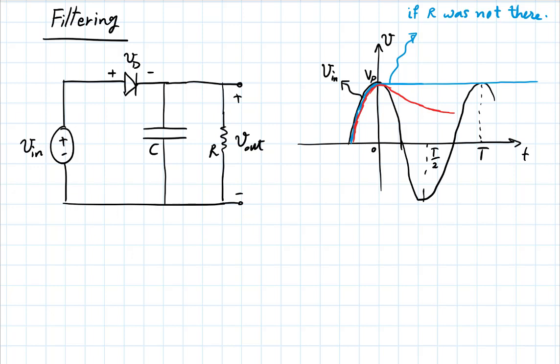Whereas in the other part of the cycle, the diode has become off. The input has been disconnected. Now you have an RC circuit, and you have an RC discharge there. It's the value of R times C that determines how fast or slow that discharge is. So I have drawn something here that's relatively exaggerated. But let's go with this.